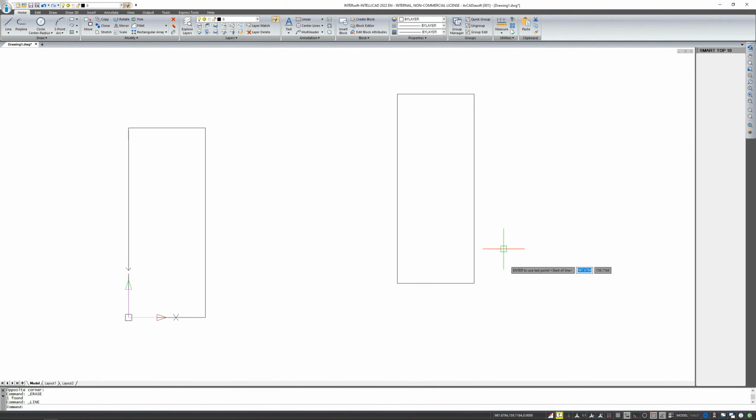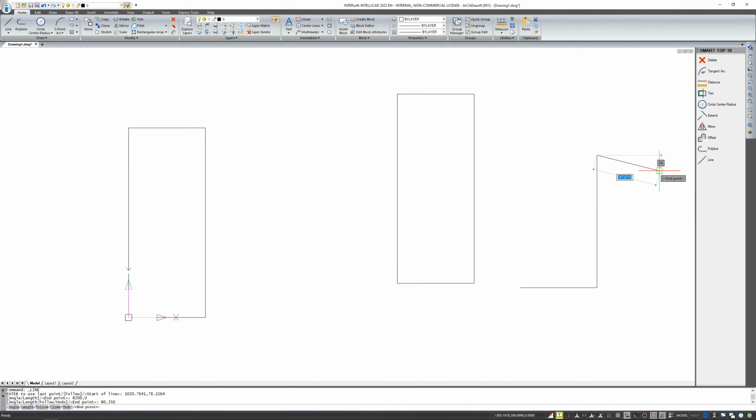When I start drawing and entering data and I realize that I have introduced some data incorrectly, for example, now I have introduced the wrong value, we have different ways of using the undo option. 1, there's the Control-Z option. 2, there's the undo from the arrow here at the cursor. And then there's 3, which is the undo option from the command area. Now, all of these undo options only undo the last entered element and not everything that was inserted from the time you activated the command.